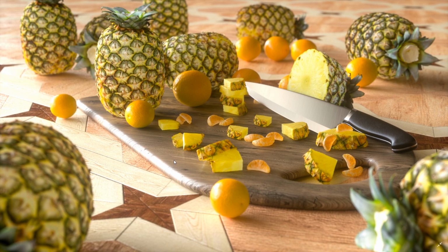But before we move on, the knife I got here was just a preset default Cinema 4D knife that they have in the kitchen section. I think it's under the Cinema 4D Broadcast or Studio folder, I forget which one. I retextured it. Basically, all it was just metal for the handle and the blade, and I used some Cinema 4D Octane noise to add a little bit of bumps and details on the handle, and a little bit of stretched noise based off of a projection to give the blade a little more detail too.